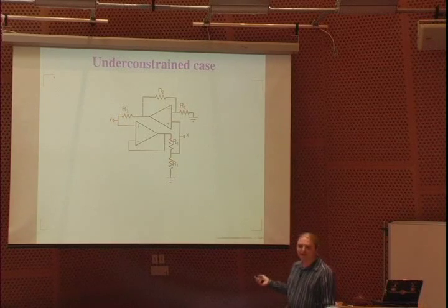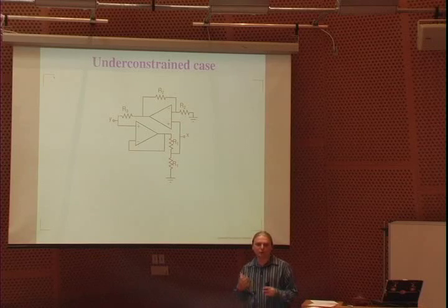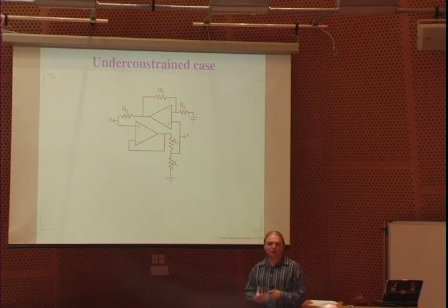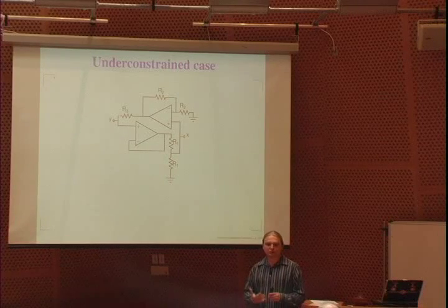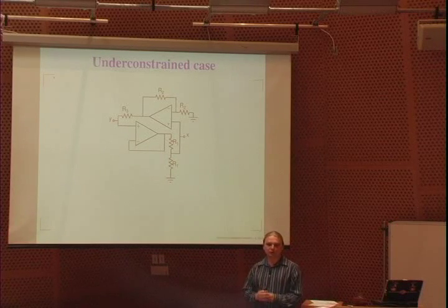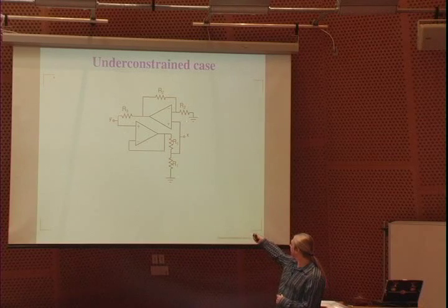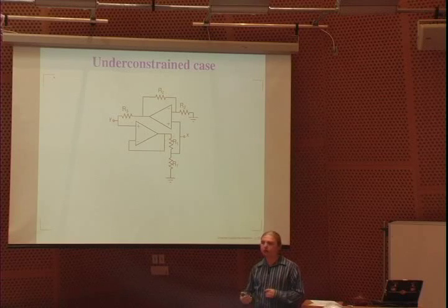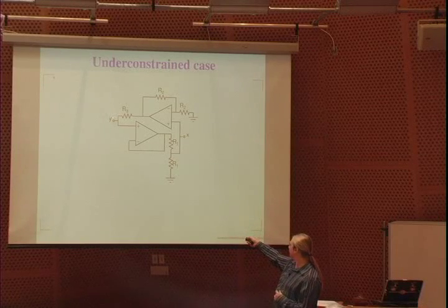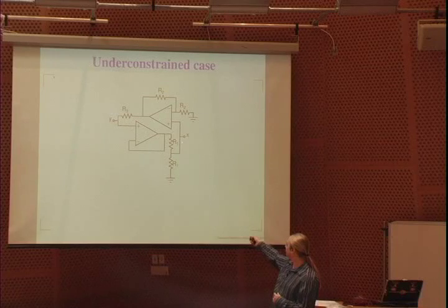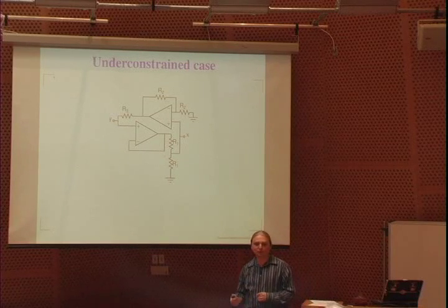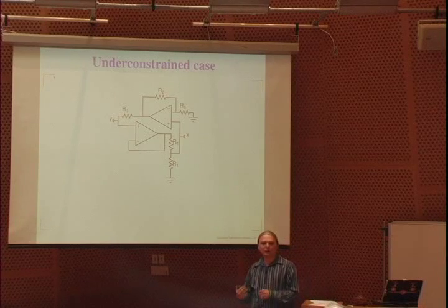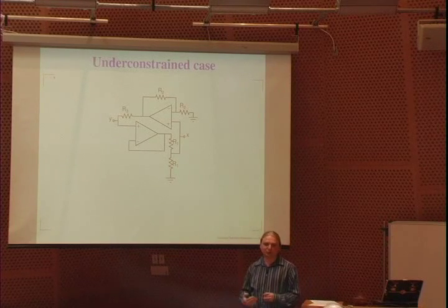So moving on, in the under-constraint case, what this argument shows by LaSalle's theorem is that we'll go to a minimum, but it doesn't say what the system will do within that minimum. So if you look at this, if the loop gain here is a little bit less than 1, this will go to, as we expect, in this case, this is solely the constraint at y equals 2x. It will go to y equals 2x equals 0. If that gain is a little bit more than 1, it will go to y equals 2x equals either the positive or the negative rail.